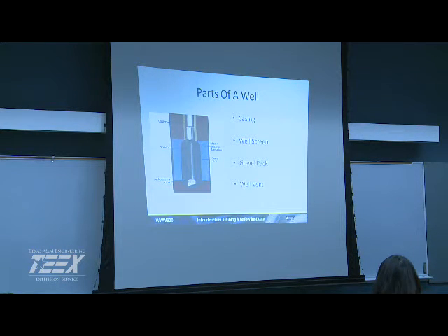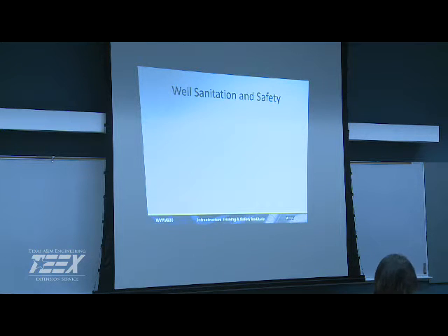We were doing a lot of this down south where we had a lot of real fine sands. So you've got to have real fine mesh screens on it, and then you have to make a big gravel pack. And then you have to be careful how you run your pumps, or else you're going to really work that sand in there. You don't want a lot of starts and stops. You want to be able to run them for a longer time, so you minimize your surging. I was going to say we use a lot of pre-packed sand packs. It's all we need down there. Yeah, so you've got to be able to put something in there to keep that from infiltrating in.